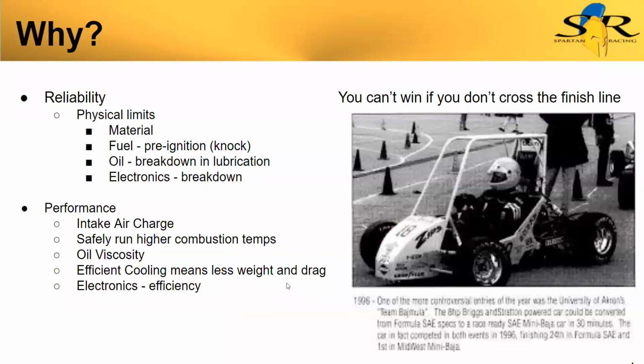So again, why the reliability of vehicles? There's physical limits to the material. If we can't get rid of that waste heat, the engine will melt, the valves will break down, you'll burn holes in them. Fuel will knock, that's pre-ignition, if the combustion chamber gets too hot. Oil breaks down, there's a breakdown in lubrication, and the engine will seize up. In electronics, there's a breakdown in semiconductors and insulators, causing short circuits.